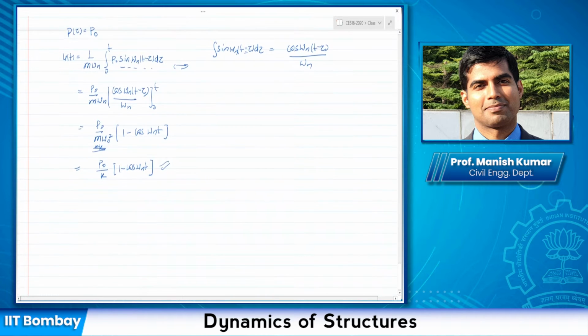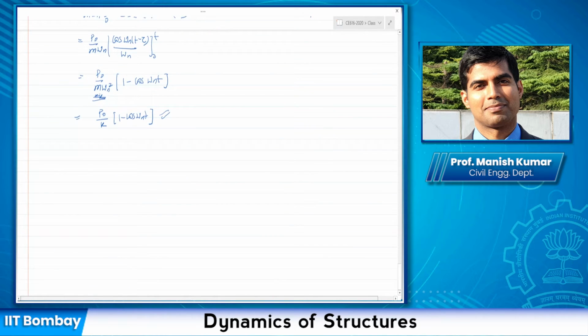So basically, let us come to a step force, which is a load applied like this. The response to this step force u(t), how would you plot this? Remember, it's a function which is oscillating, but it is now shifted by P naught by k. Okay, and what is P naught by k? This is the peak static displacement subject to the load P naught.